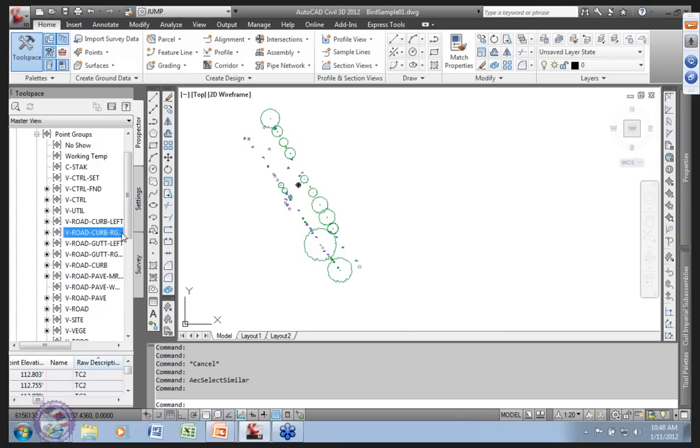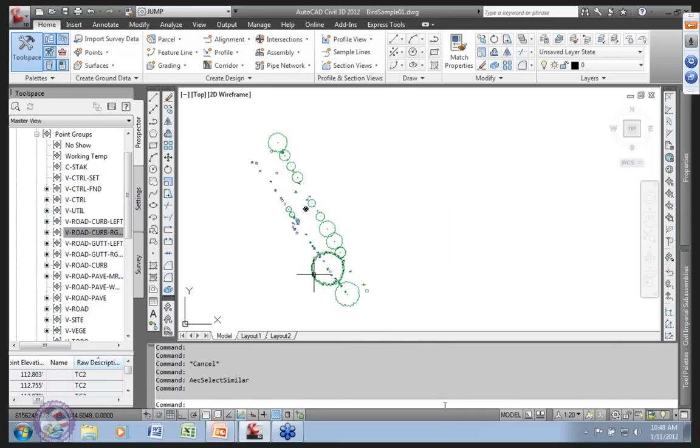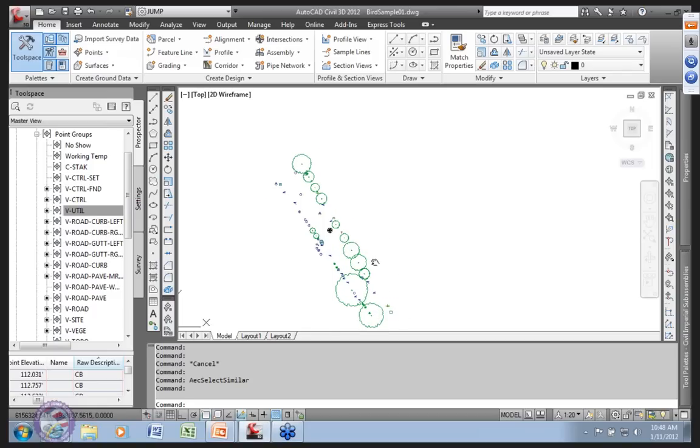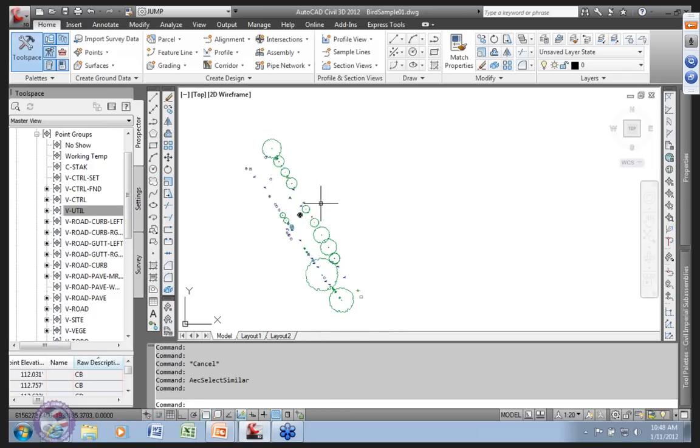So given that I have that, now I can do things like labels and block rotations really quickly. We can do this for labels, but if I had a utilities left and a utilities right, and built that into my collection method, or my import process, or what I did with the description, I can do an awful lot of things repetitively and quickly in terms of changing those rotations and getting that all fixed up. Reduce as much as possible the individual work that you have to do.